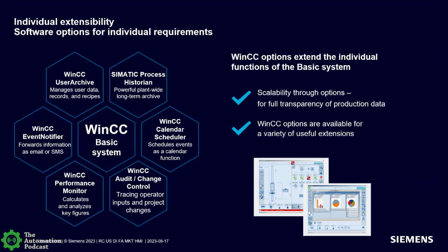Event Notifier helps forward alarm messages via emails or SMS, and it provides a calling chain for either those emails or the text messages that says, hey, if the first person doesn't answer, let me escalate it. Let me escalate this to the second, escalate to the third. So it's just a way that you don't always have to be monitoring the WinCC to get notification that something's going wrong or something needs to be done.